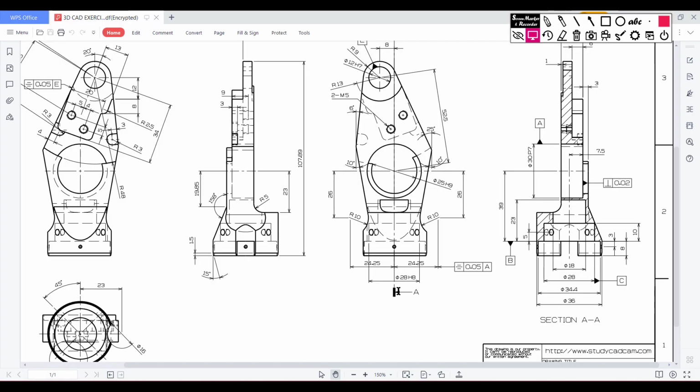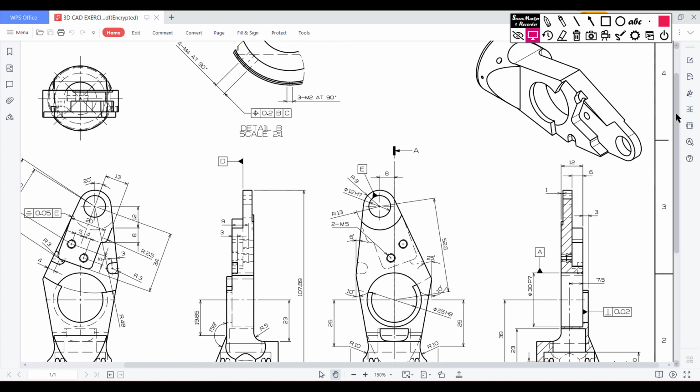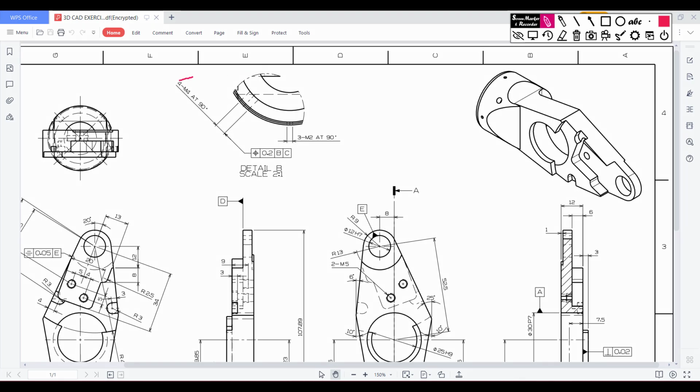Okay, now go to our sketch, and in our sketch we can see that we have M4 cut. So for the M4 cut I am going to use the 4 diameter circle here. If you want you can use M4 hole widgets. Okay, so it is about a 45-degree angle. Here I will first draw a 45-degree plane, then from that 45-degree plane I will draw that M4 cut. Means I will draw a four diameter circle cut.